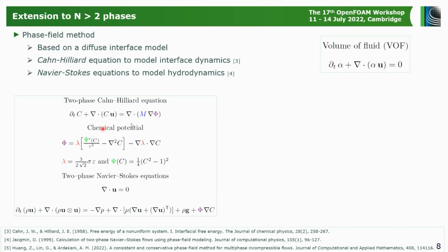Now, the story of where these terms are coming from, there are a lot of papers about it, but the main paper, the best one, is by Cahn and Hilliard, which started this work. It is basically coming from the concept of free energy of a system. If you describe a system of non-uniform composition, and we take the variational derivative of the total free energy of the system with respect to its composition, we arrive at the chemical potential, which models the kinetics or evolution of the system.